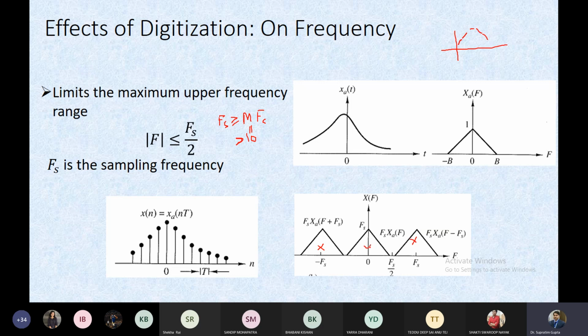So it means that by using the anti-aliasing filter, we are making our signal band limited. And if you see in Shannon's sampling theorem, this is one of the key terms: the input signal must be band limited. If it is not, then decisions on the sampling frequency would be difficult.